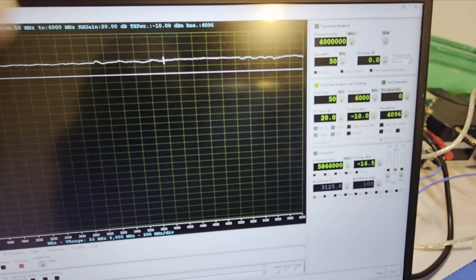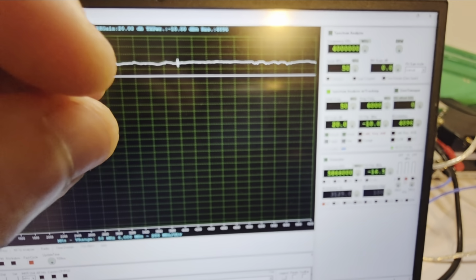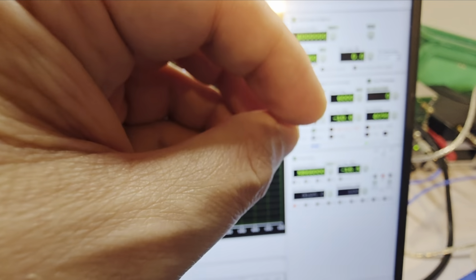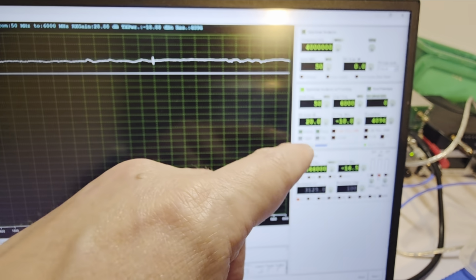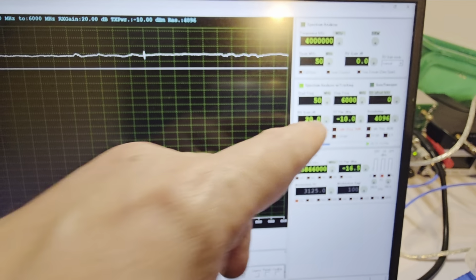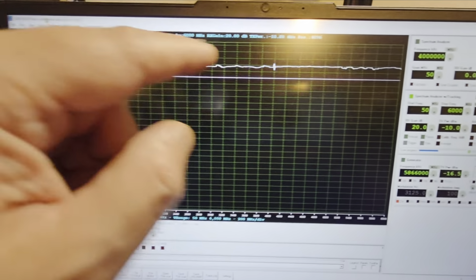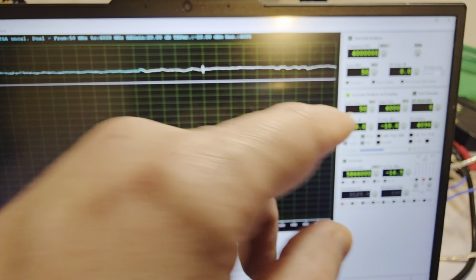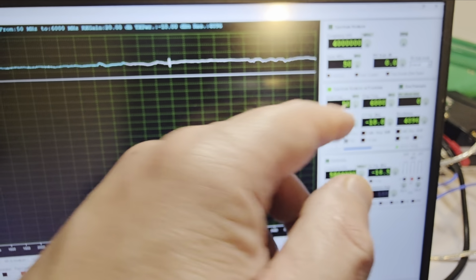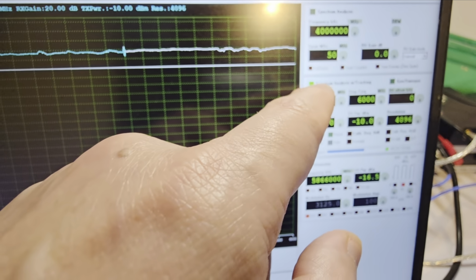It won't be the one that gives me the most dynamic range, but maybe I can get 10 decibels more of dynamic range with a different setting, raising the gain, but I will lose flatness, especially at the end. So maybe you lose half decibels, but in the tracking generator it's less important because you can normalize like a real one and make the zero.